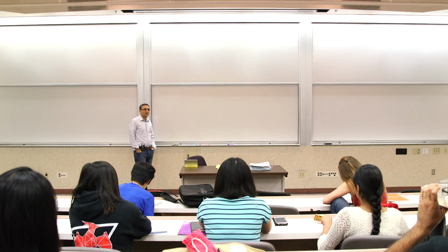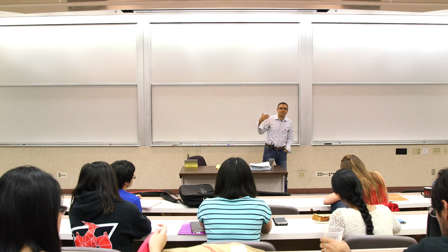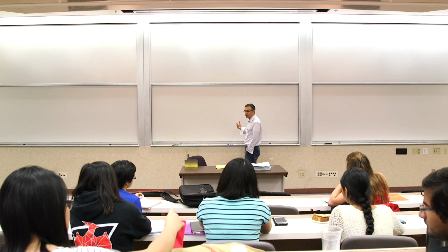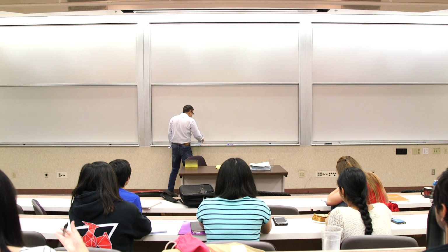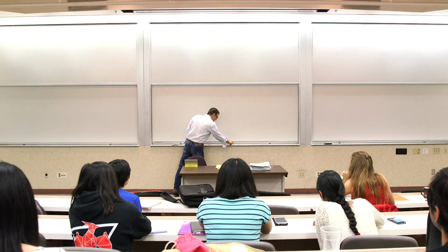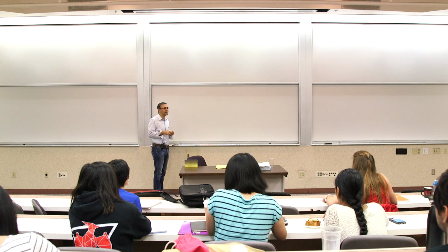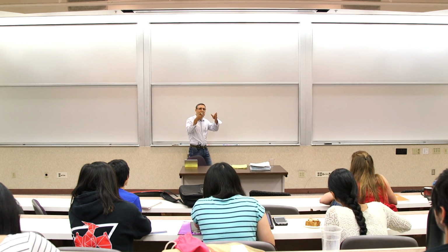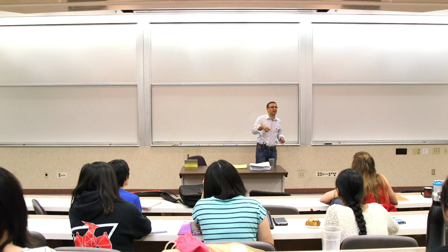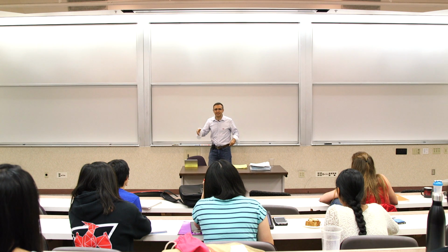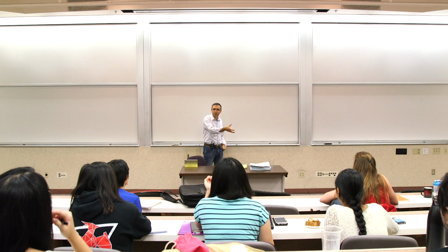Good morning. So today we are going to continue our discussion in using the Heaviside Operator for determining the responses of the system. And today actually we've built up to this point and we can take an important step today. So far what we've done is that we've defined systems in terms of a Heaviside Operator, right? So we had systems and we defined the system operators, capital H of P, and said, okay, if you have this capital H of P, it operates on the input and it produces the output, right?